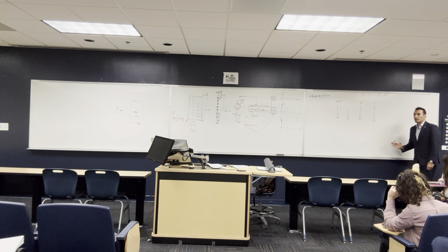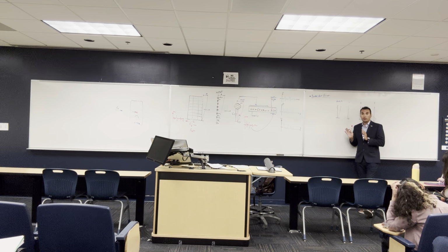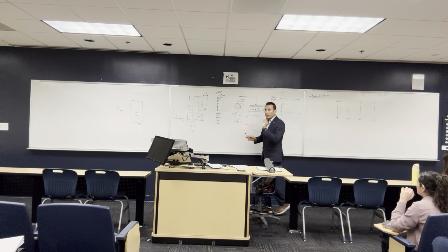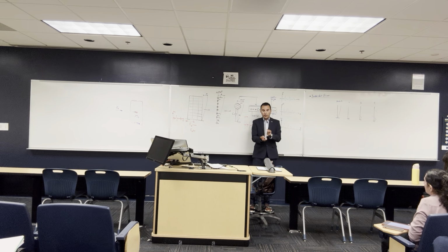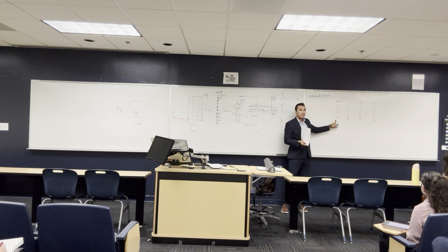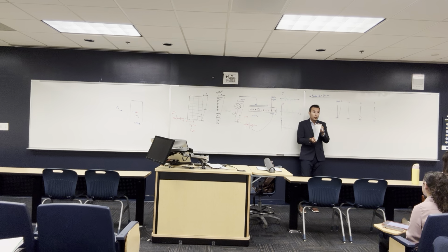And I told you last time that the building doesn't only move with one mode. It's a combination of all modes. Some of them are very, very small that you cannot notice, and some of them you can notice. If the building is moving, this is not 100% of the movement. This is maybe 90%, and there's a bunch of mode shapes that contribute a little bit to this movement at the end, okay?